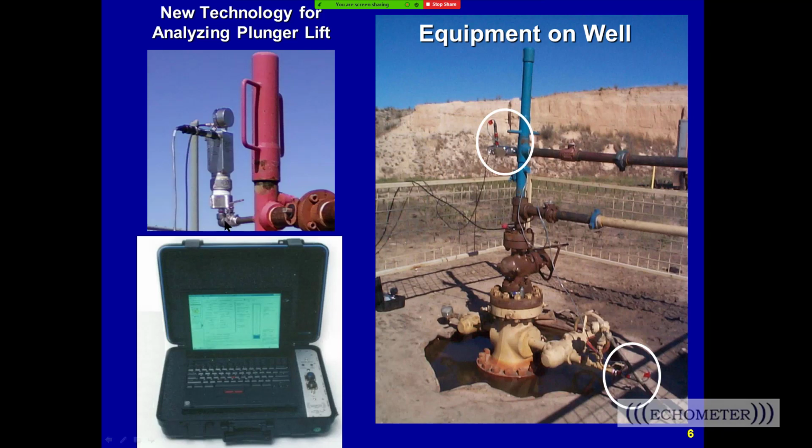All right, so a needle valve is like a little pin that blocks the signal. So you really don't want to have a needle valve here. You'd like to replace the needle valve you have on the well with a fully opening valve. You don't want to tie the gun directly to the well, because that means you're going to have to shut the well in, and that will change the cycle and won't be stabilized conditions. So you would like to have your gas gun vertical so that any liquid that comes in during unloading will run right back out.